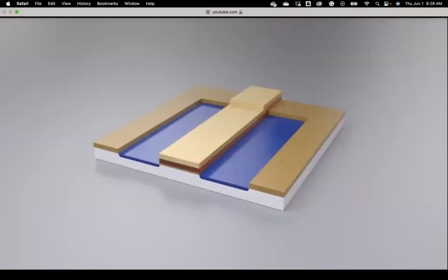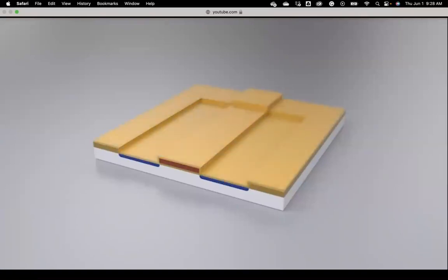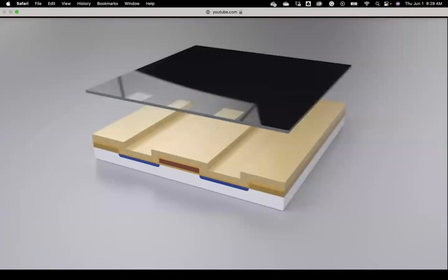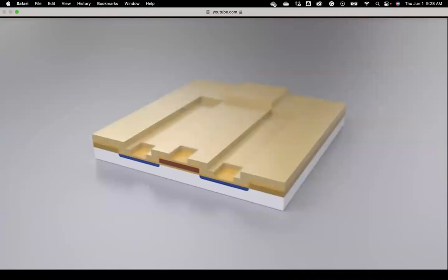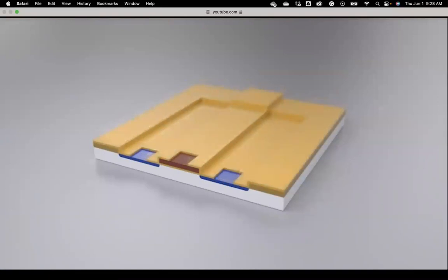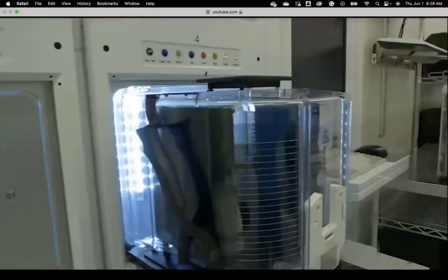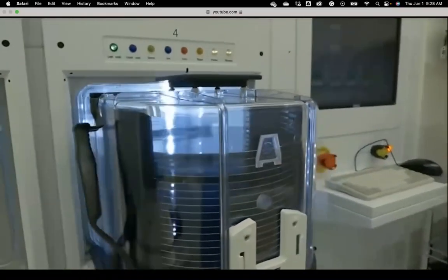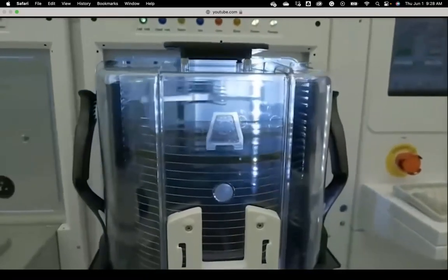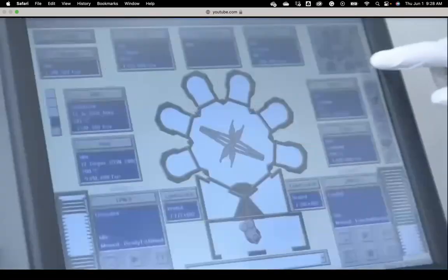After the photoresist residue has been stripped, another oxide layer is applied. The wafer undergoes another cycle of applying photoresist, exposure through the mask, and stripping. Contact holes are etched to provide access to the conductive layers, enabling the contacts and interconnections to be integrated in the wafer. This is done by depositing metal alloys onto the wafer in sputtering machines.